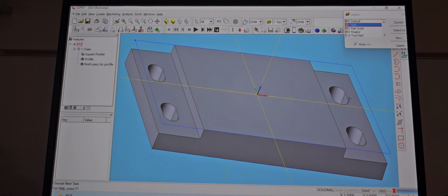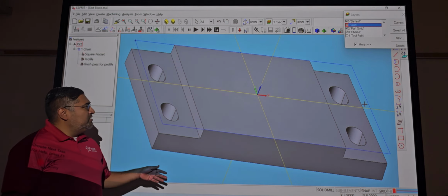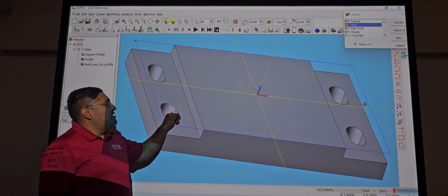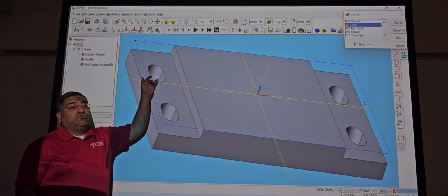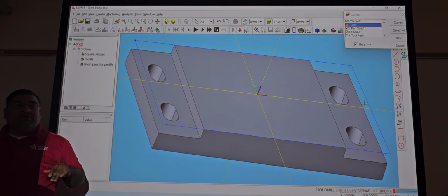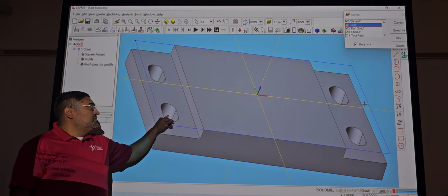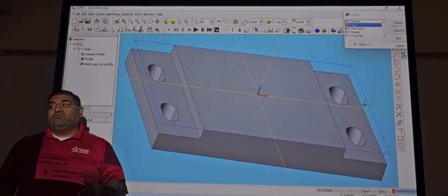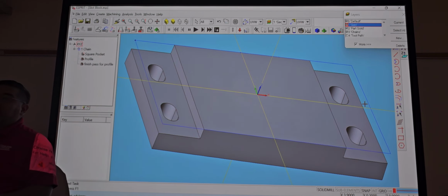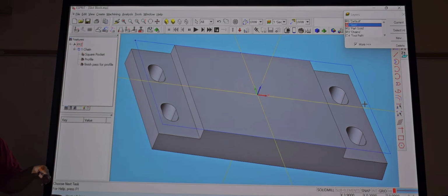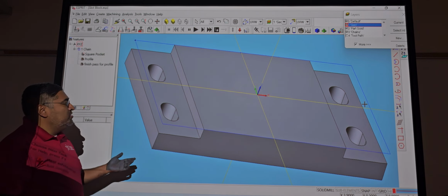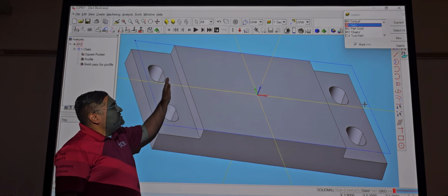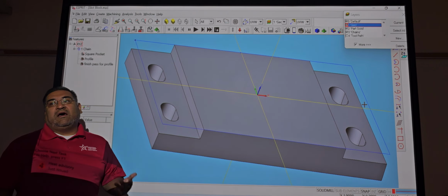And then do this slot, correct? Because depending on if this material is like Inconel, why would I want to cut 375 thousandths if another tool is going to cut it anyways, right? And then when I do the slots, I'll probably have to use a smaller tool than a 1/2 inch, right? Because of the radiuses. Sometimes the radiuses might be smaller, correct? So what I would want to do is cut this step first, not the slot first.